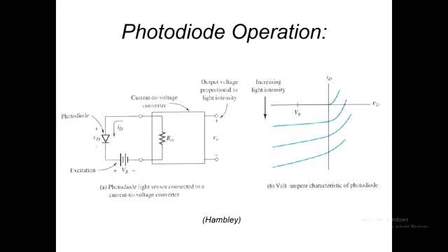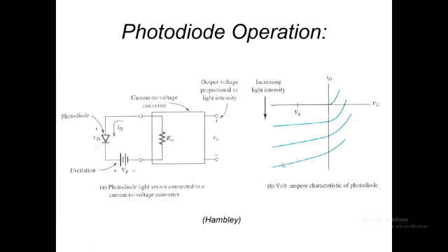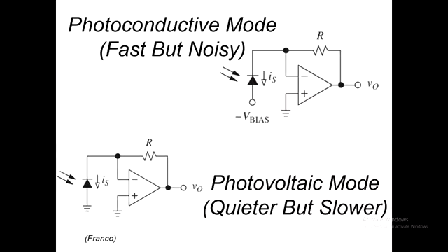Photodiodes, as I said before, we can put some bias on a diode to make it more reverse biased, and that will mean that we can get a greater light sensitivity from the sensor, because there's a broader collection area in the depletion region.